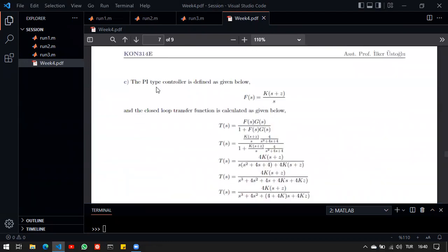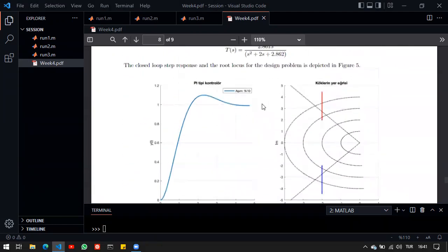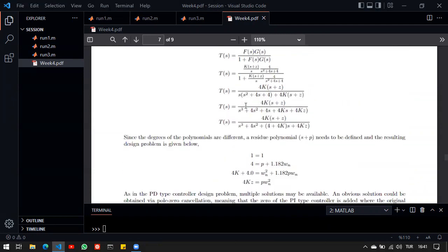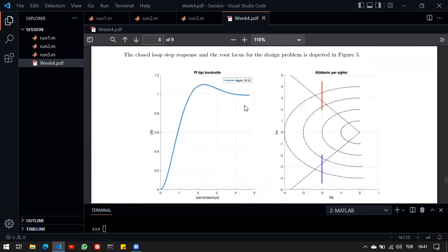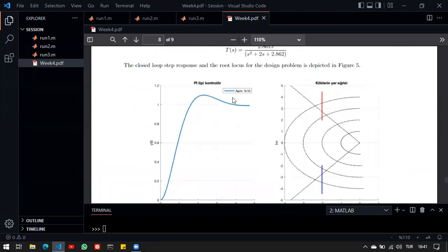And we've also seen that the PI controller is somewhat similar to the PD type controller, but with an additional pole at the origin. But this exact difference here is also the difference for reference tracking. So if you add an integrator, 1 divided by s is an integrator, or a pole at the origin to the system, then you can track reference type references perfectly.